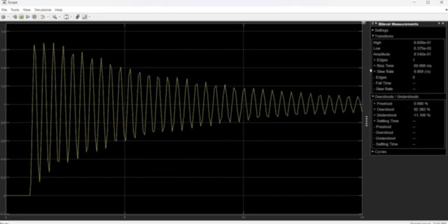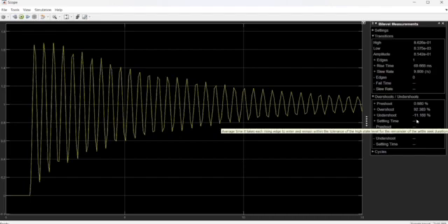The rise time is 69.668 milliseconds and the overshoot is 92.383%, while the settling time has not occurred. When the settling time does not occur, it indicates that the output for this graph is not stable.